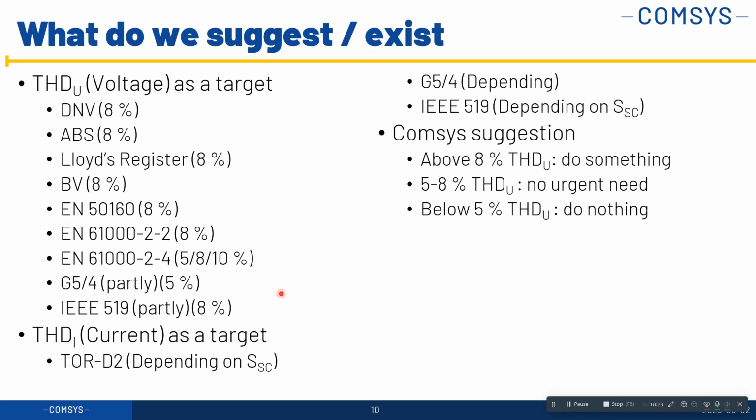But in Europe right now we're seeing at least half of the compensation need compared to the US, and that is because the US is going so strongly on the current limits of the IEEE 519 to make sure that everything is so far down in the voltage distortion that it's very, very expensive to do a compensation. Yeah, so it would be very interesting what you listeners think about this. We're quite harsh against IEEE 519, how it's written right now. The intent is perfectly good, but the current distortion levels are really easy to misinterpret, so it would be better to go with the voltage distortion level.